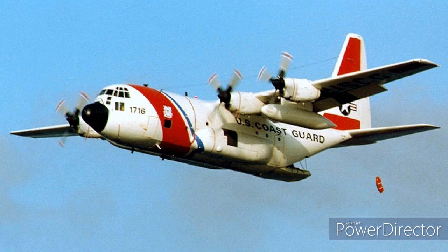If the major cause of contamination is salt ingestion, as might be the case with an aircraft which flies for long periods low over the sea, like this US Coast Guard C-130, then a timely rinsing of the compressor with fresh water can avoid the use of harsher treatment which otherwise would be required.